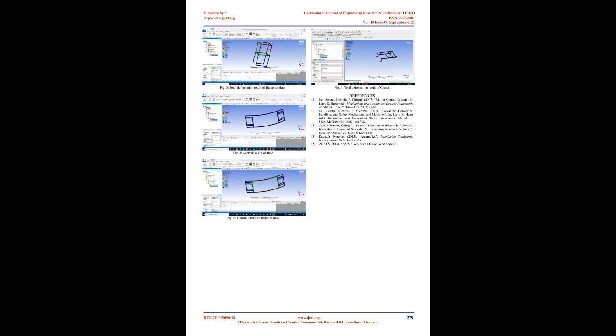For rotors, mass equals 0.3 kg. Radius equals 101 mm or 0.1 m. Acceleration equals 1 m/s2. Torque equals 0.3*1*0.1 equals 0.03 or 3 kg/cm. Taking factor of safety as 2, we get torque equals 6 kg/cm.